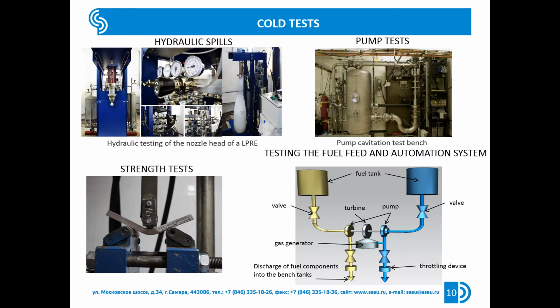Autonomous turbine tests can be carried out with natural gas, but more often model working fluids such as air or other gases like freon are used. When checking and testing the control and regulation system units, testing operation within a specified life cycle or number of switching operations, determining and adjusting their regulation characteristics, and studying the effects of various external factors on the operation are carried out.